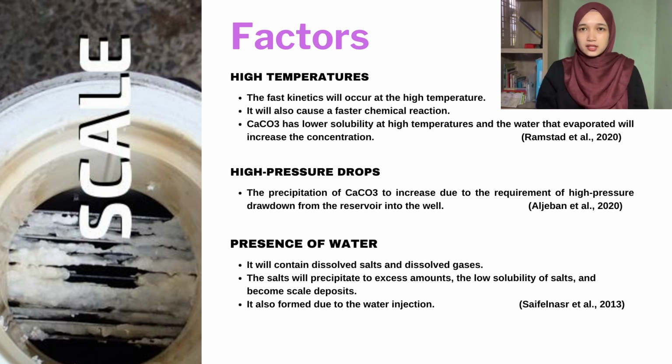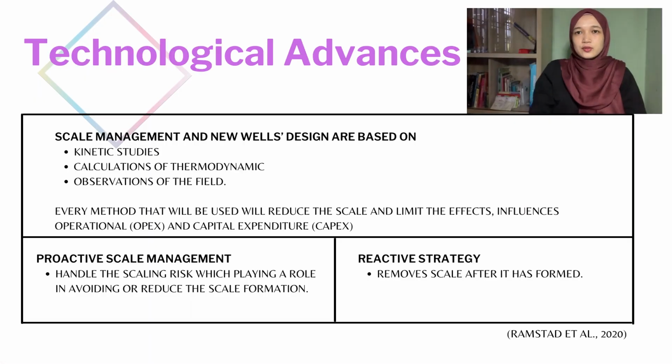The last one is the presence of water. The water will contain dissolved salts and dissolved gases. The salts will precipitate in excess amounts due to the low solubility of salt, and become scale deposits. Next, it's also formed due to water injection. So the next slide is about the technological advance that can improve the scale management and new well designs. It is based on kinetic studies, calculations of thermodynamics, and also observations of the fields.